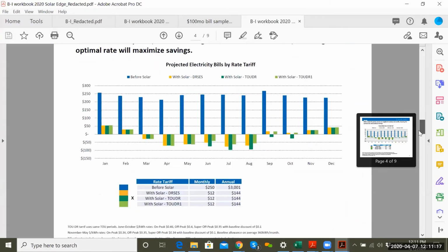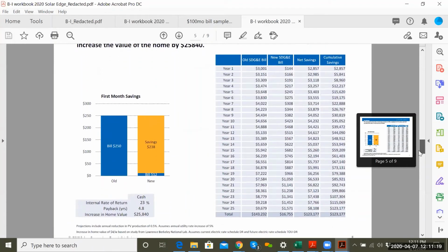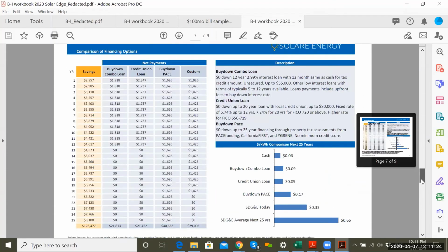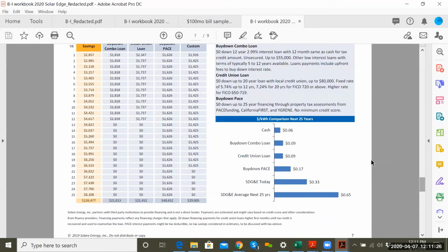I think most of the challenges now, from an install standpoint, because it's so new and much more complicated, are the battery installations. Something as simple as the little current transducers, little CTs that measure the current flow through wires, are clamps that you clamp around a wire. If you put them on upside down, it will screw the whole system up, and they aren't labeled clearly on which is up and which is down. And then there are all kinds of other potential grounding issues with the battery, since there's so much more backfeed going through that.